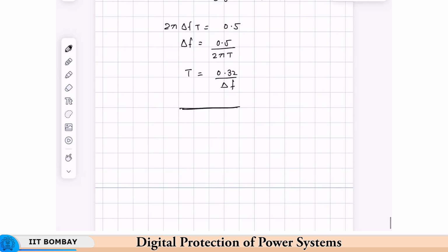For three-phase signals, we could use either the current signal or the voltage signal, but generally the voltage signal is preferred for calculation of system frequency, because the current could contain harmonics, characteristic harmonics, and in general more noise. Also, the current can vary over a large extent throughout the day or any period, because the load can vary.